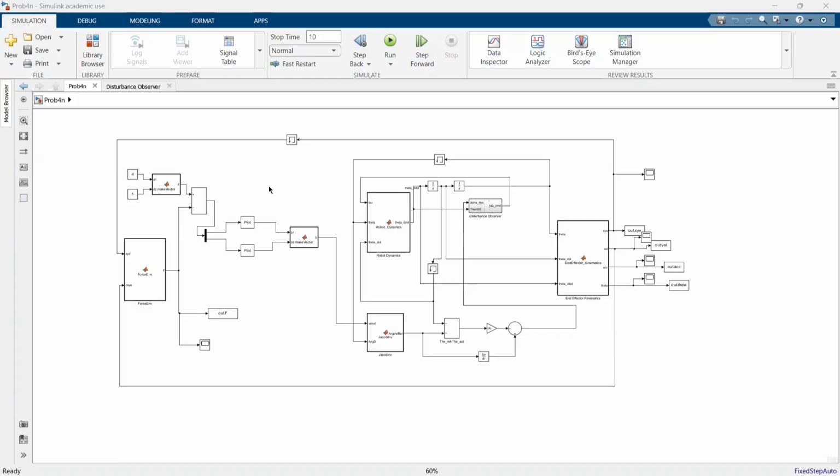The target was to pull left with negative 6 Newton in X and push up with positive 5 Newton in Y. The environment acted like a passive spring and damper. It can only push back if it is hit; it cannot grab or pull the robot.